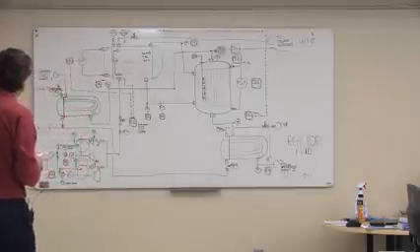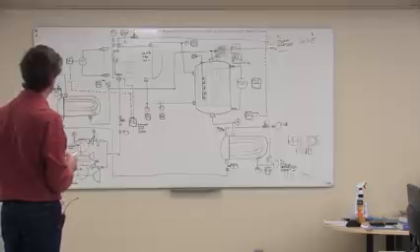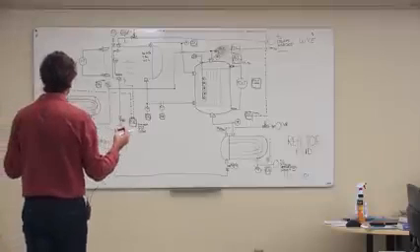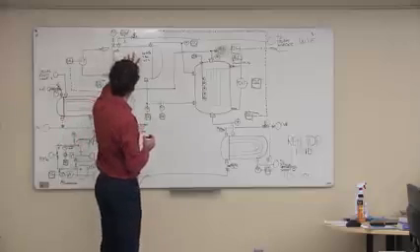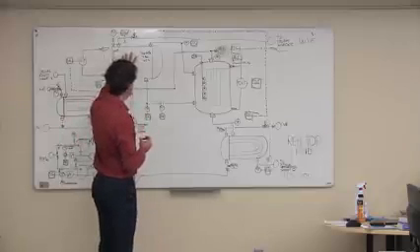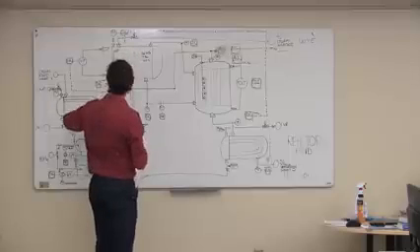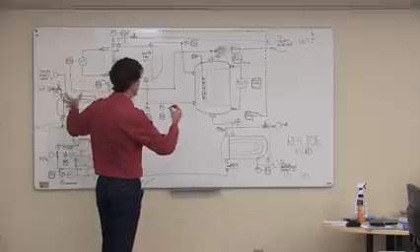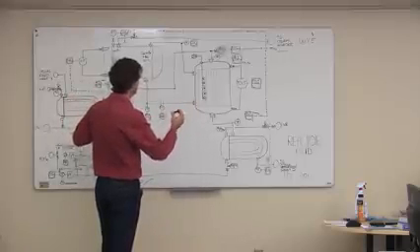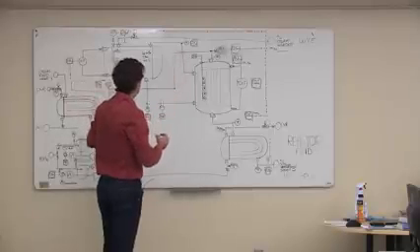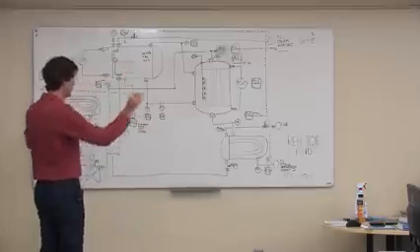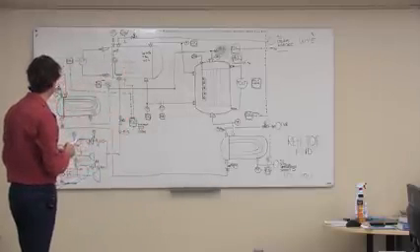So I think that's the basic process control system. Did I miss anything? We're controlling the inventories in the system. So here's our inventory of water on the water side. Our inventory control on the gas side, there really are no control valves on the gas side. So the inventory is really the inventory of the whole loop. And that inventory control is kind of done with this PIT and PIC system and some other manipulated variable.